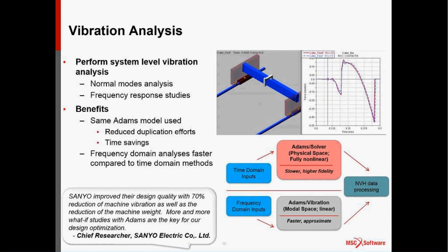First, using Adams Vibration, you will be able to calculate the system natural frequency under different conditions, and also evaluate whether or not there's a resonance between your system natural frequency and the operating frequency of some of the components or subsystems inside your product. You will also be able to evaluate results in the frequency domain.